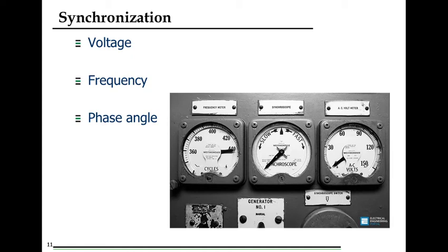This means in a phasor diagram, if we see our RYB phase, that is 120-degree phase displaced, it is running at a faster speed than the grid RYB phase. And so if it is running at a faster pace, then a time will come when this will overlap or superimpose on the grid RYB phase, and after that time it will again pass that. So we need to close the breaker at the time when the RYB phase of the grid and RYB phase of the generator superimpose.